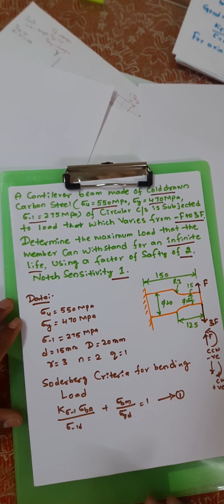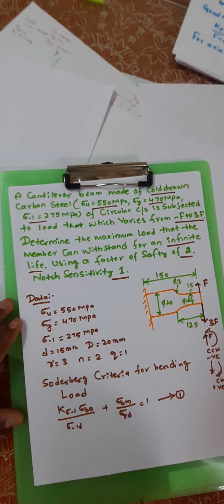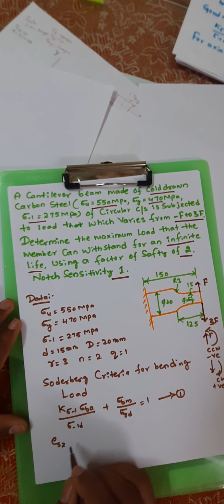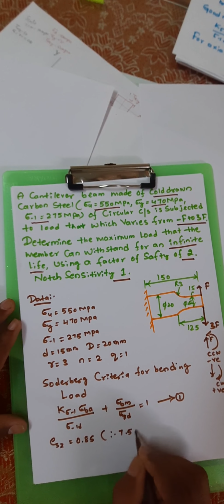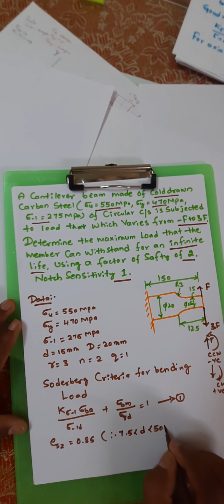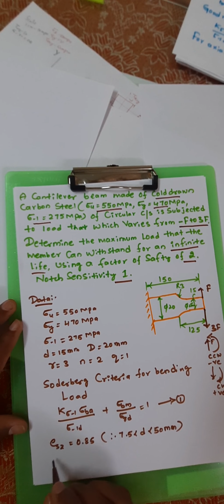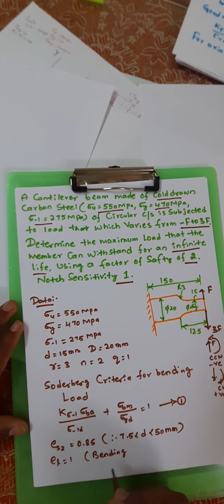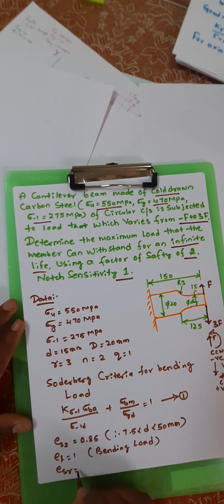Before we find all these things, we need to find the stress concentration, and also note down some of the important correction factors. Consider ESZ, the correction factor with respect to size, which is 0.85, for a diameter greater than 7.5 and less than 50 mm. This is a notation we already discussed in the theory class. Also EL is equal to 1 for the bending load. If it is not given for bending load, you need to consider EL equal to 1, and ESR is equal to